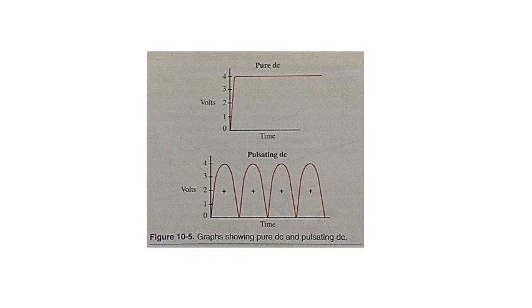A stronger magnetic field can be created for this improved generator by replacing the permanent magnets with electromagnets. Field coils can be placed over pole pieces or shoes that are fastened to the steel frame or generator case. The revolving coil, or armature, is suspended in the case, resting on proper bearings. The single coil is replaced by wire coils of many turns on the armature.